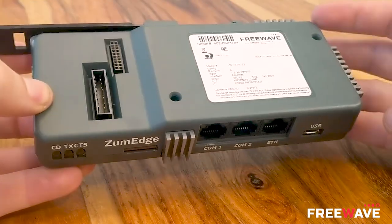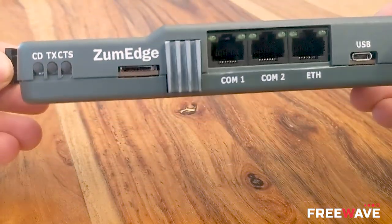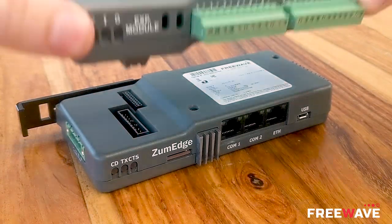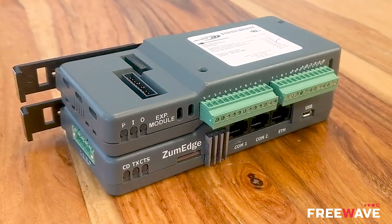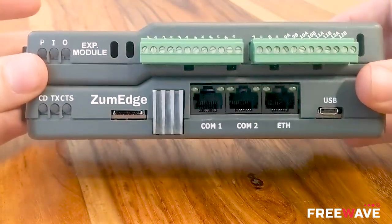The ZumEdge product comes as a DIN rail mountable radio base. It has 2 serial ports, 1 Ethernet port, and a micro USB port for configuration. To add I/O to a ZumEdge base, you simply snap on an IOEX expansion module. We support up to 15 expansion modules, and each IOEX module provides 12 I/O channels.